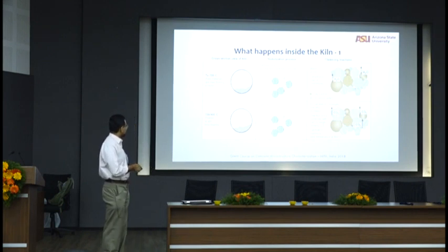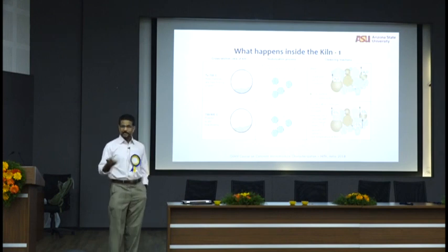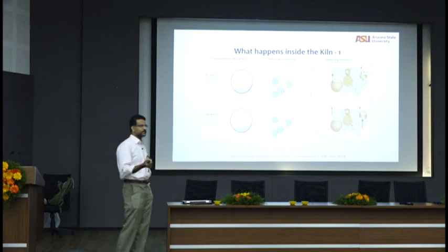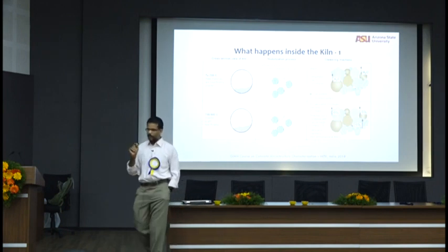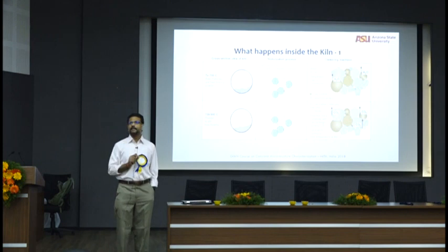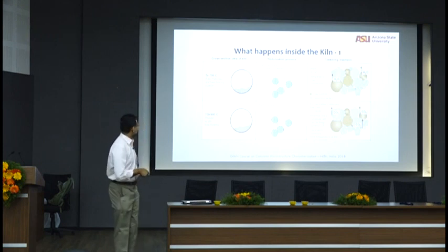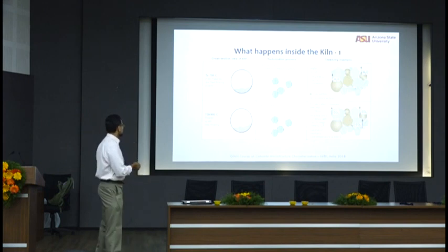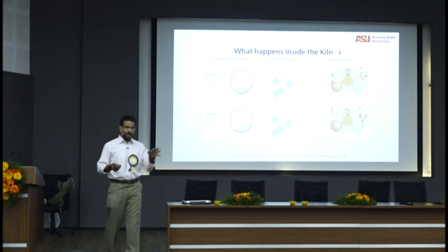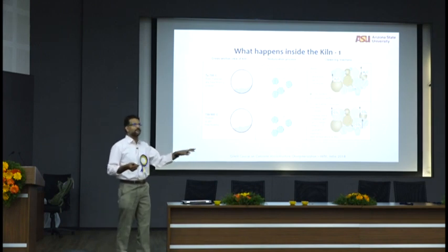And then you have silica, free lime combines with CaO to form C2S. C2S is the first compound that is formed. There are reasons why I am going through this, but I'll talk about that. So C2S, dicalcium silicate, is the first compound that is formed, and that happens before 1000 degrees Celsius, 700 to 900 typically. Okay?